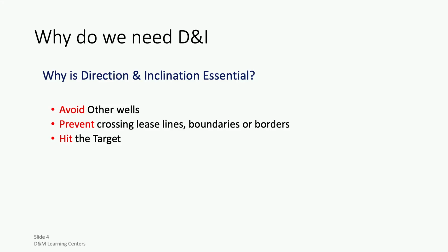Why directional drilling is essential. One, to avoid other wells. That's probably our biggest thing, is to not hit another well. You hit another well, that's bad news. You can burn the rig down.